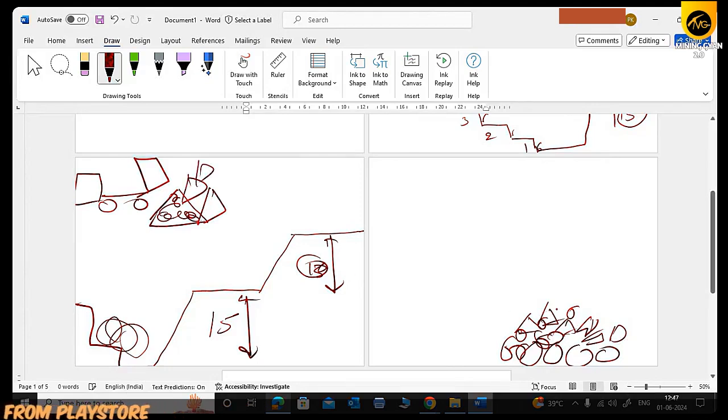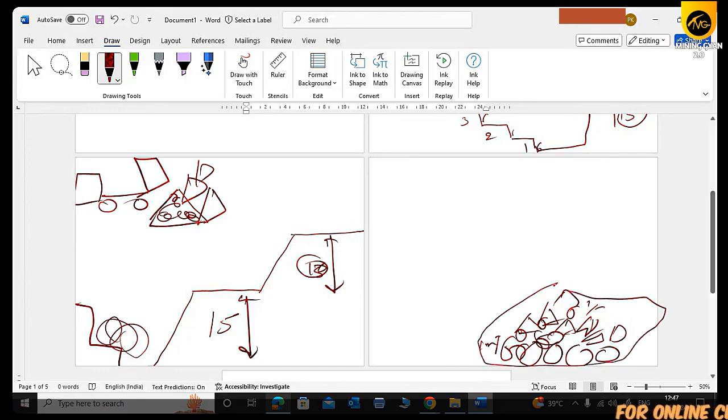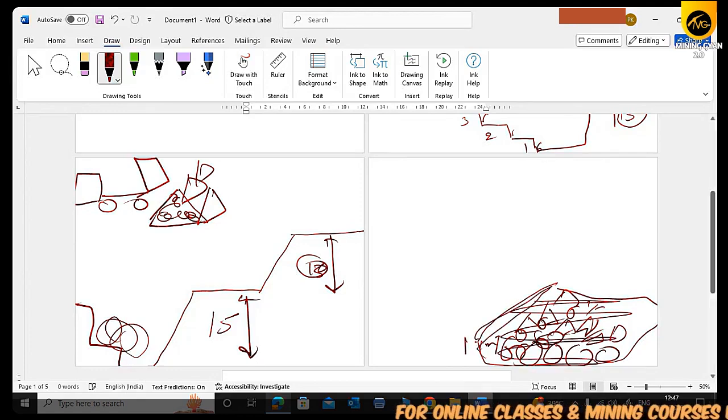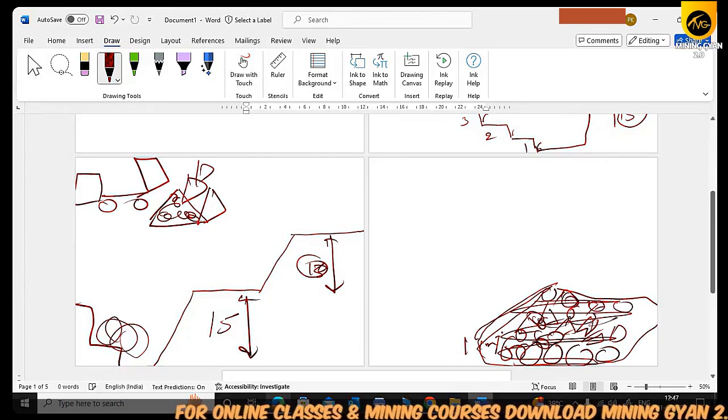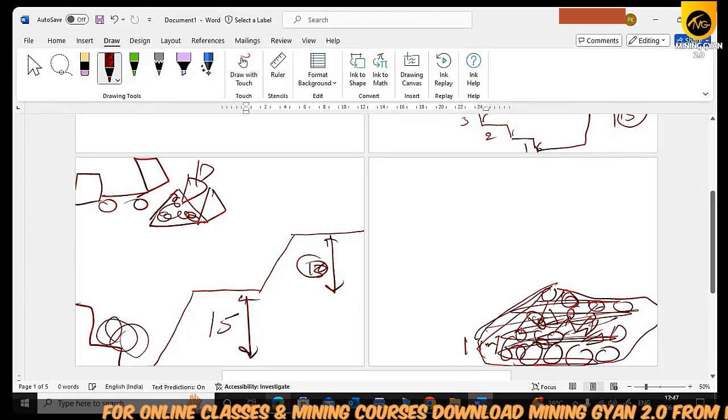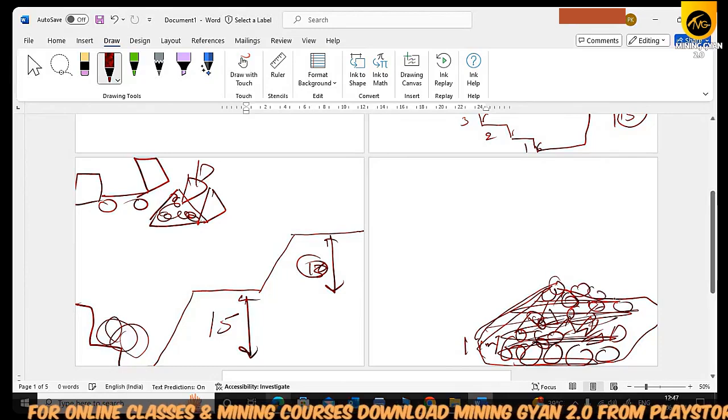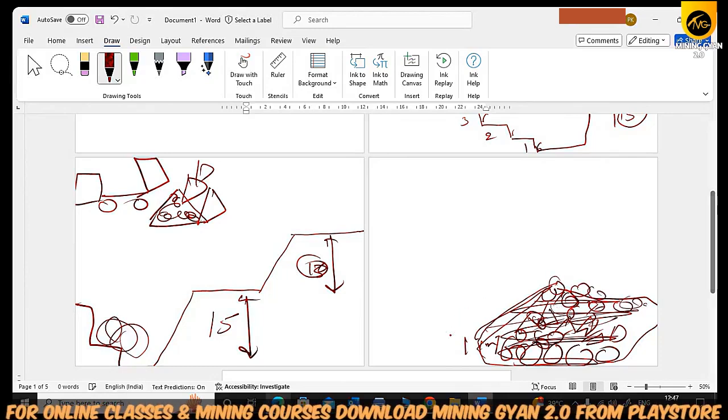After trip dumping, it will be a height of only 1 meter. The dozing will go here, and the dozer will push the material like that, so it becomes a height of 1 meter. Again we maintain the trip dumping over here, and again the dozer pushes the material. Again we push this to 3 meters height. Likewise it will become the first 3 meters.